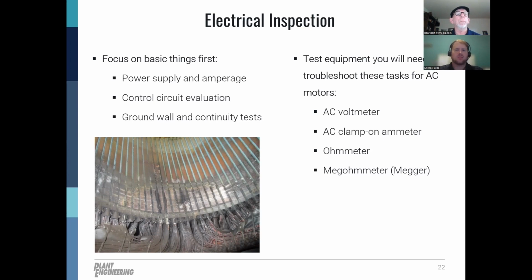So the applied voltage could be direct wired from an on-off switch or circuit breaker. It could be coming from somewhere a little more complex control, like a soft starter or variable frequency drive. When you are checking the voltage from the control circuit, like a variable frequency drive, you want to make sure that the power is available at the incoming and outgoing side of the drive in run mode. If it's not, then you trace your problem back to an issue with that variable frequency drive or with that soft starter.